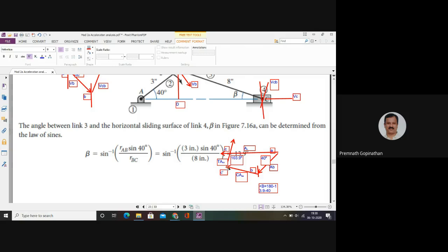Okay, now you can identify the line AC dash based on the magnitudes and the counter angle at B. Once AC dash is identified, the counter angle at C is known, so you can use the sine rule again to identify the other vectors as well.